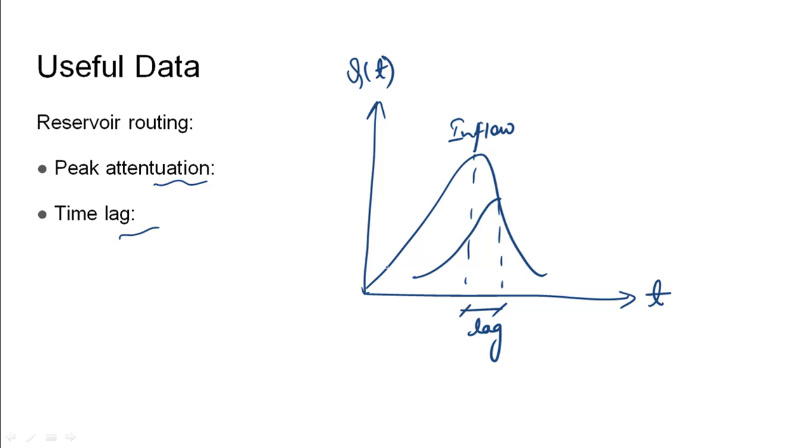This is because the reservoir will reduce the flow which is in excess. And it is also noted that between the peak of the inflow and the peak of the outflow, there is a certain reduction, that is called as peak attenuation. It is also noted that the peak of the outflow hydrograph is formed on the recession limb of the inflow hydrograph, as it can be seen here.